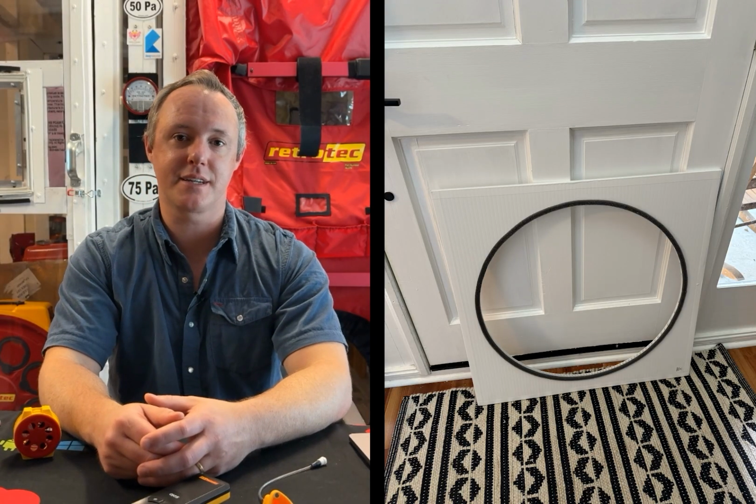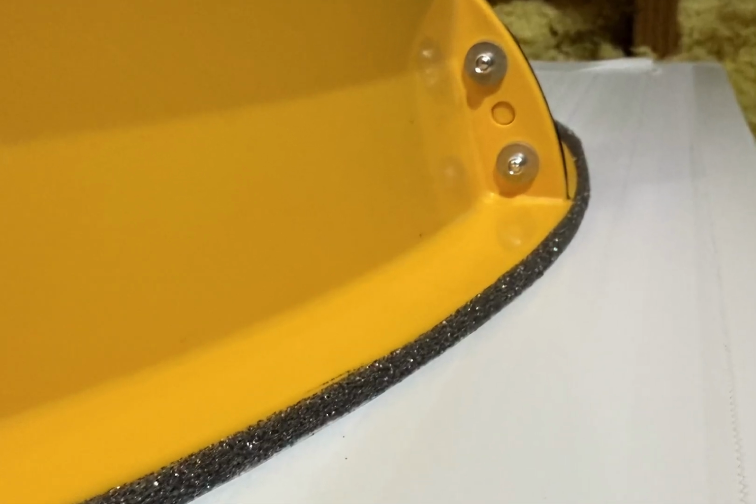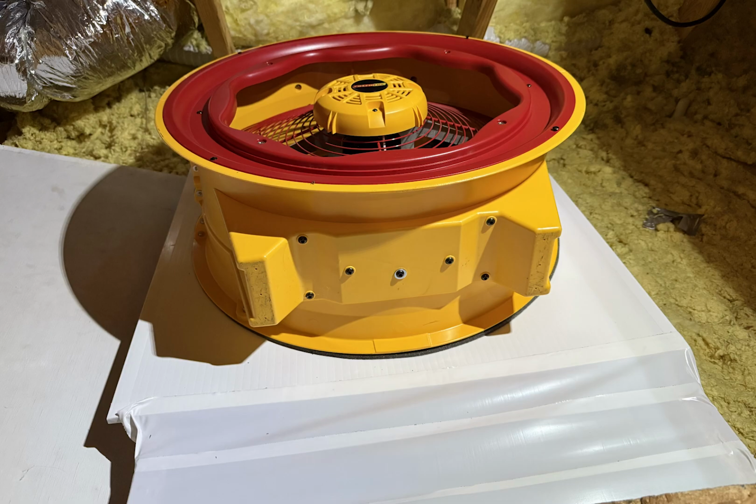And if you're choosing to use a second blower door instead of a duct tester, that plate that we manufacture that comes with a leakage split kit, if that's what you like, you could actually make your own out of plywood, get a router, cut out a hole for your fan, and you can put weather stripping around it. And then tape off the rest as you need to there at the attic access.